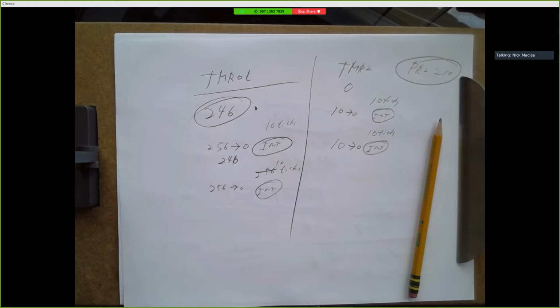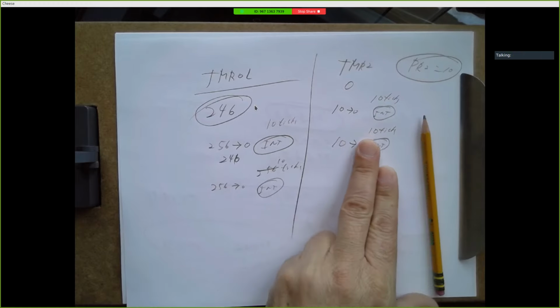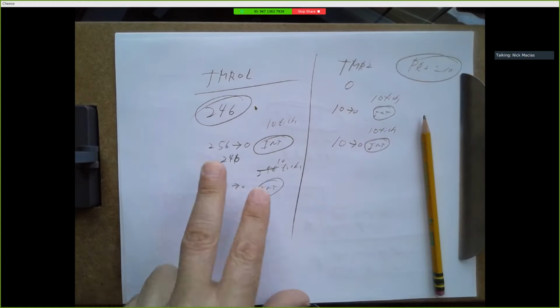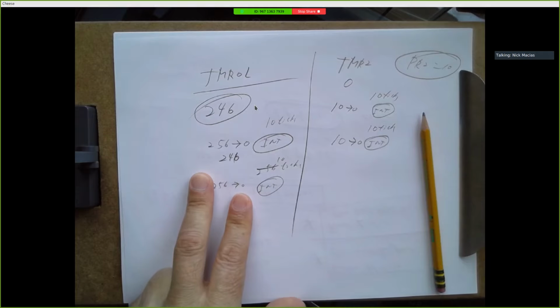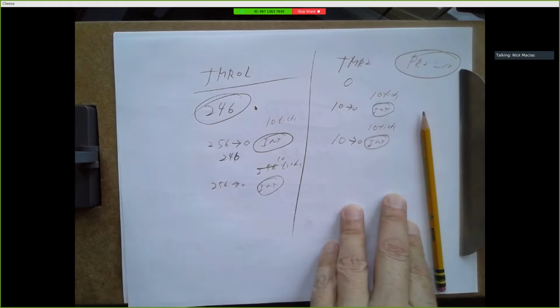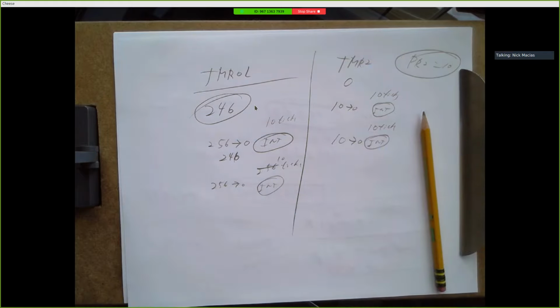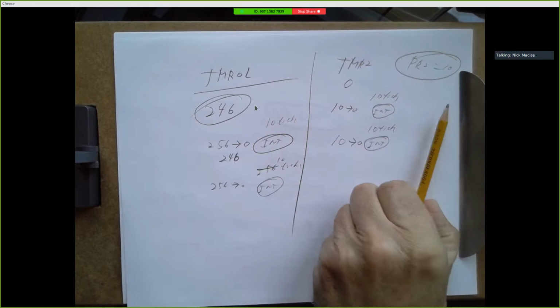Let's see, can we use a strategy for timer 0 in Lab 5? Well, I don't know what strategy you mean, because this is only for timer 2. But you do something like this in Lab 5. If you're using timer 0, you have to continually reload whatever value you want it to start at, which I think is 0 in the demo code. Or you could use timer 2 in the lab if you want. It may be a little more complicated because of the period register, but either of those would be fine.